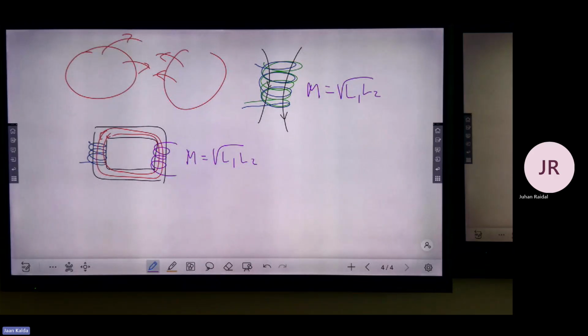Mu, the permeability, depends on magnetic field strength. So it is not completely linear, meaning that if you let sinusoidal current in, the voltage that appears on the second loop might not be exactly sinusoidal. And sometimes you might want to avoid it. You might want to have exactly sinusoidal, in which case you take this so-called air core loop, air core transformer.